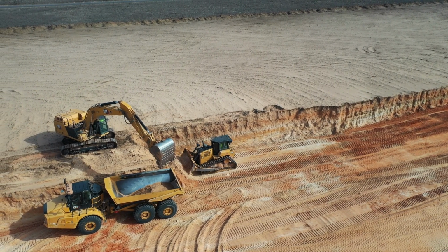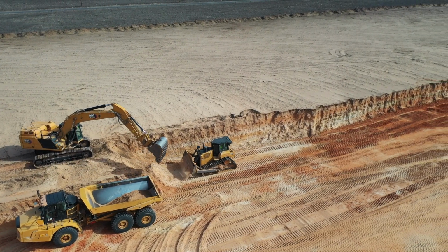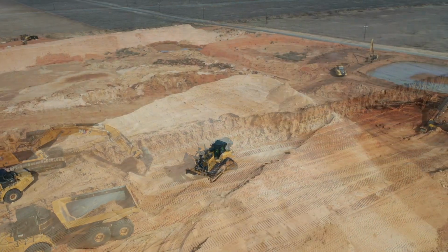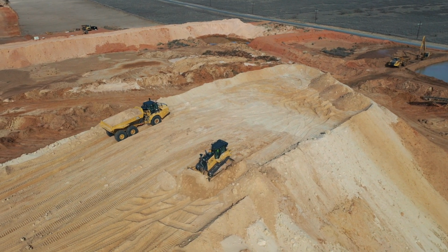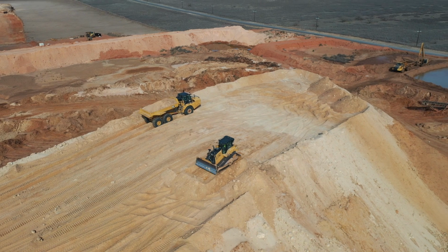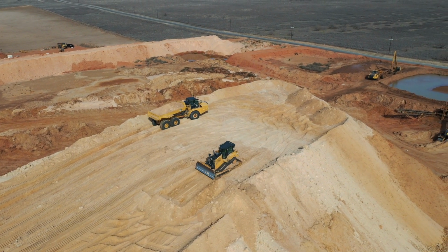If you need to turn a dozer while pushing material, use the dozer tilt or clutch only. When dozing soft or unconsolidated material, be aware of changes in the footing under you and immediately back out of material that feels like it is softening.